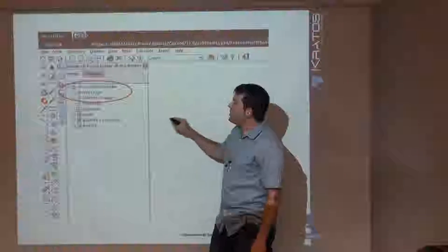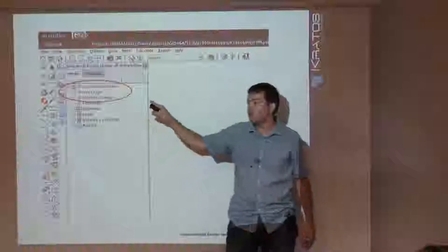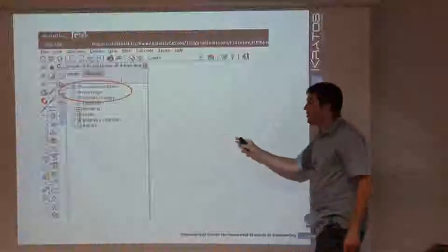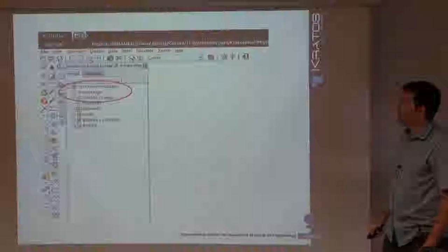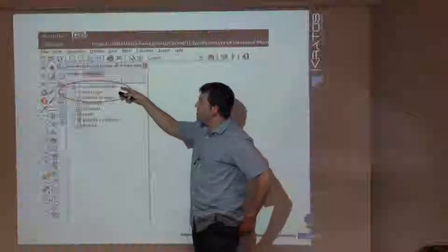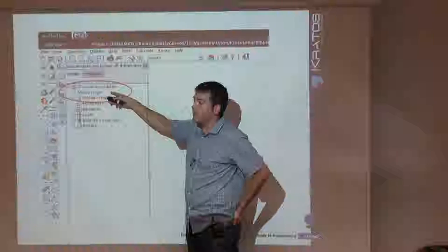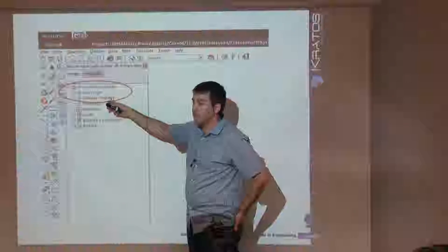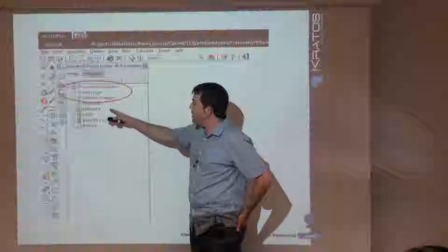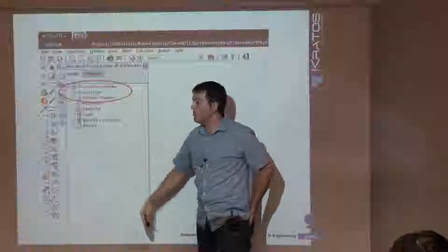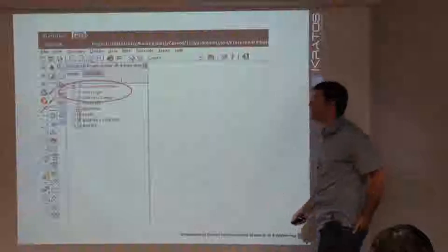With the structural simulation, the things that we have done with the wizard is just selecting the things for the structural simulation that we have already selected. So when it opens these menus, we can see a little bit. It says structural simulation, it says analysis type, right? Solution and strategy, properties, it means the properties of the materials that we are going to use, elements, loads, boundary conditions, and finally some menus for the results, for seeing the results.